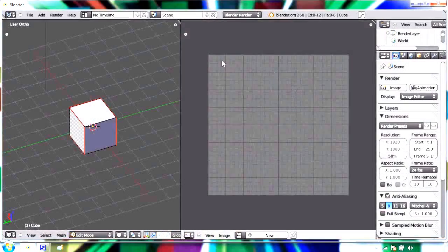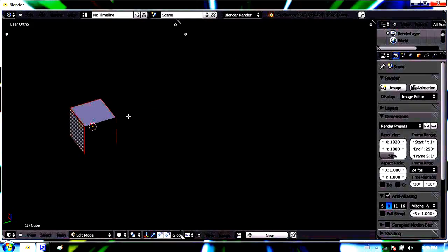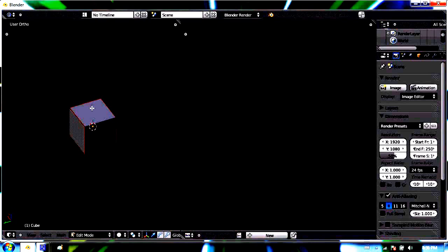I'm going quickly because this video can only be about 15 minutes long, and I have had to make it a few times so that it fits into that short length of time. Okay, I'm going to switch into face select mode so we can lay out the faces. But you'll notice that because this window is narrower, I can't see my face, edge and vertex select modes. So I'm going to middle click down, so press my mouse wheel down, and then drag this left, and that's how we can scroll or drag the header.